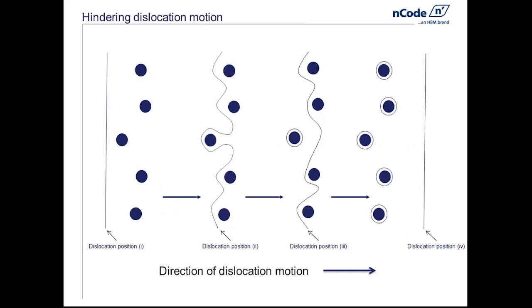A demonstration of how dispersion strengthening hardens up the material. If you look at the extreme left, I've got a line, an imaginary dislocation as a straight line that I'm wanting to move across those particles, which are the spherical or circular lumps in the material. So I'm pushing on the metal, and the line of the dislocation starts taking a convoluted appearance as it tries to form around those particles.